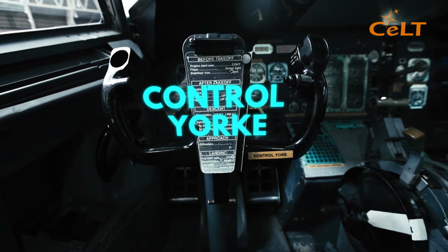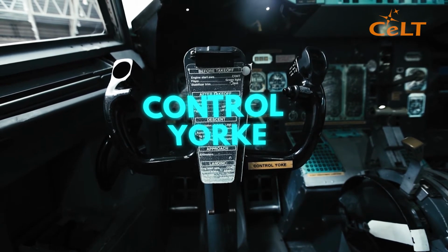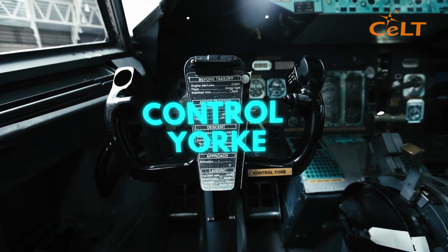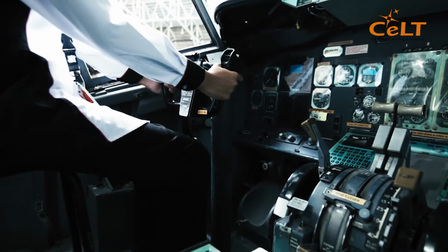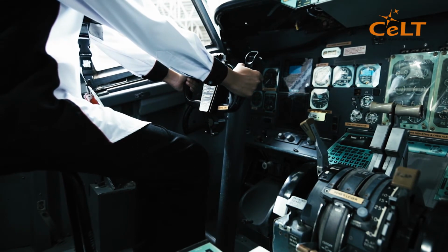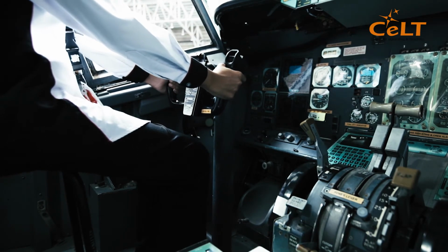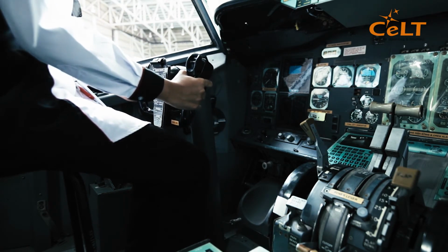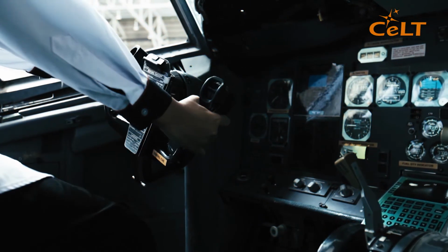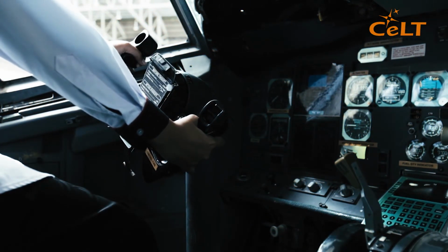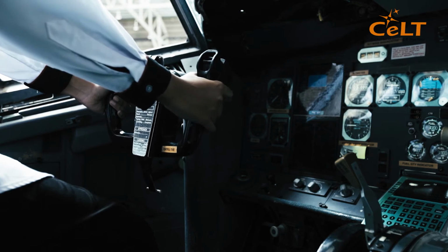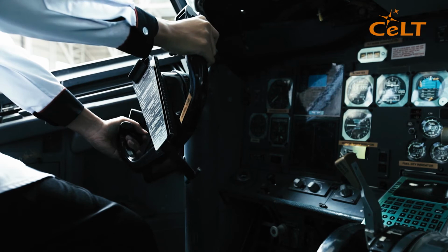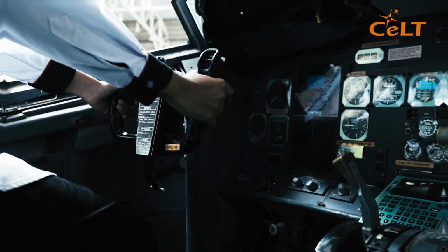Control yokes. A yoke is perhaps the prototypical flight control, positioned right in front of each pilot. It controls pitch, nose up and down via pull and push inputs, and roll, left or right, via left or right inputs, and may control trim as well. However, pitch and roll can also be controlled by a stick, as in some Airbus models.